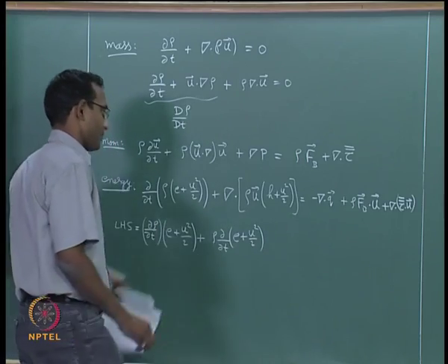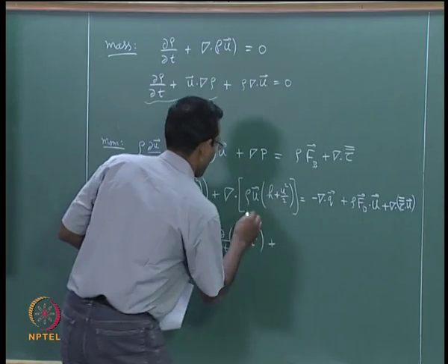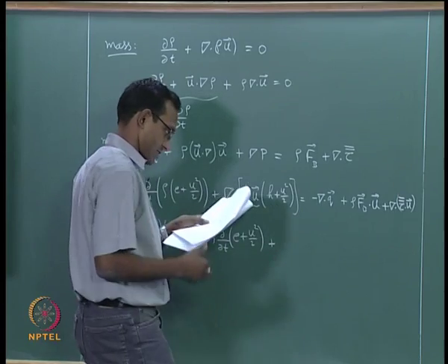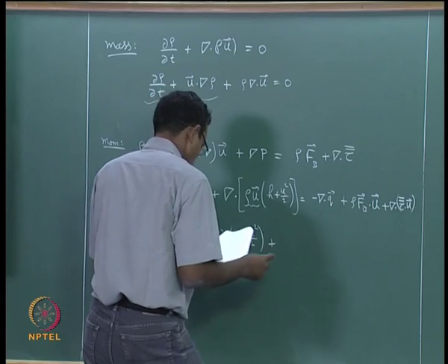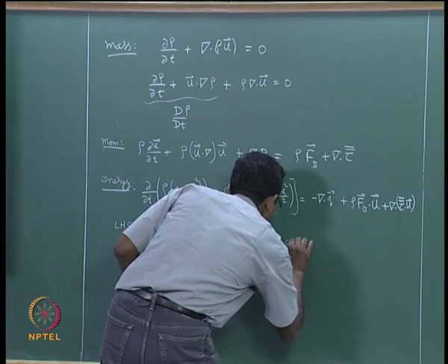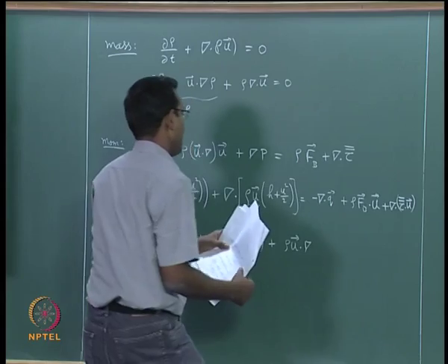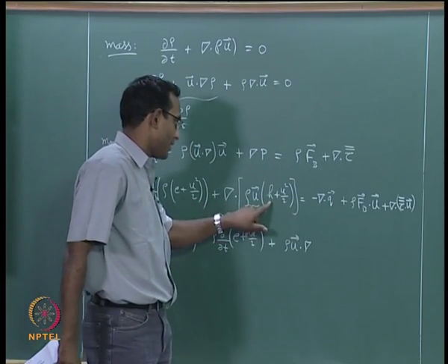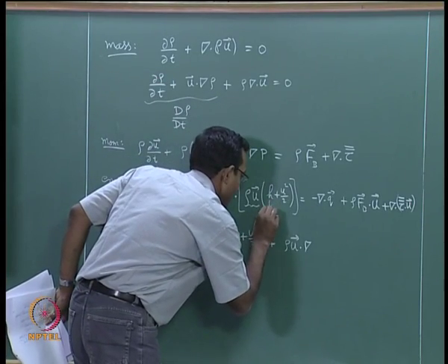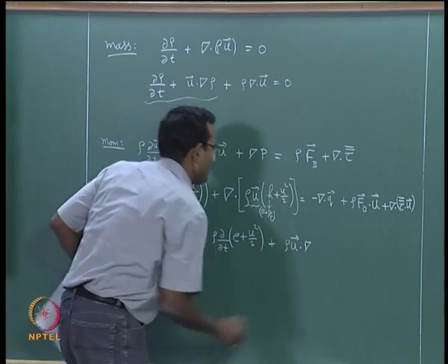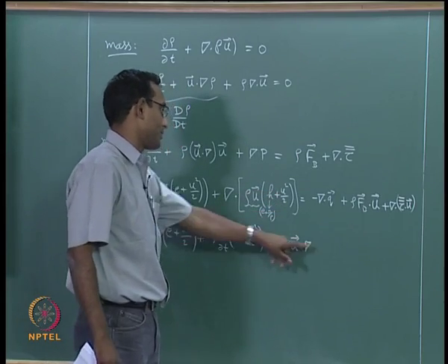This is coming from the first term alone plus the next term. Again we have to do similar thing. I am going to group this rho u together and the bracket is another term we will keep. If I keep the rho u term together, ideally I should have del dot of h plus u square by 2, which I want to write. I will write this right here, E plus P by rho. I will put h as E plus P by rho. I will take this E and this u plus u square by 2 together and write it here.